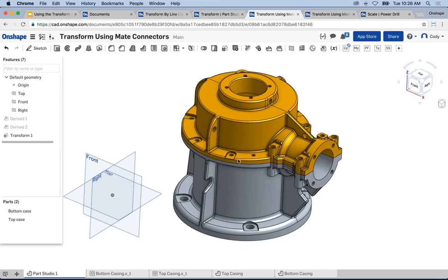And now you'll see what I mean, but it's very similar to mates. Now you need to define the mate connectors beforehand, but then just bringing them together is very similar to the fasten mate at the assembly level. Just click the two mate connectors, brings them together. You can specify flip directions and secondary axis if you need to, and you can also edit the mate connector to get it exactly where you want it. And I'll show you an example of that right now.